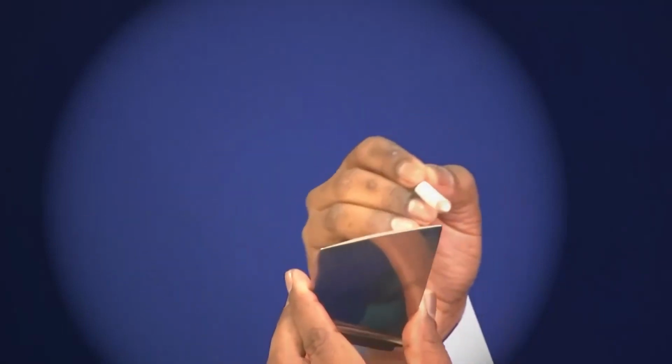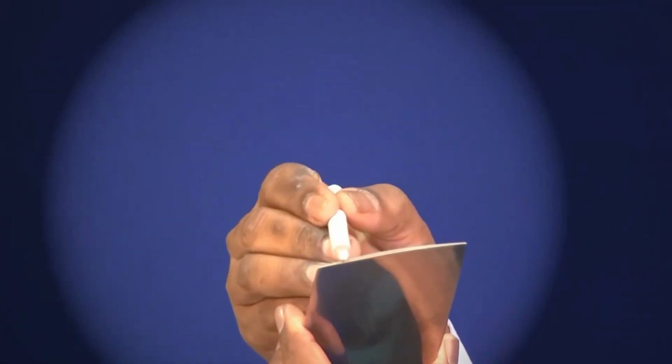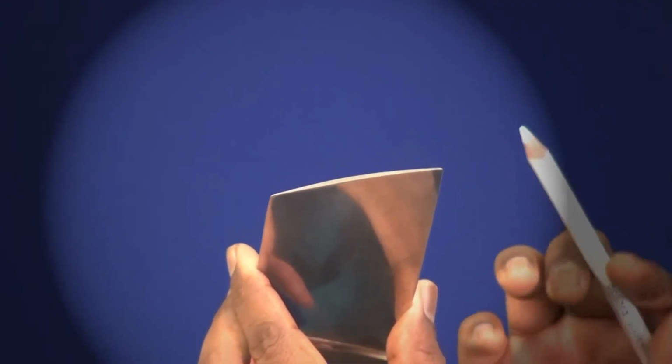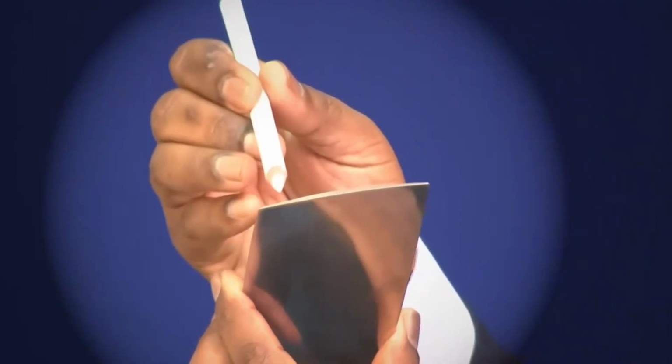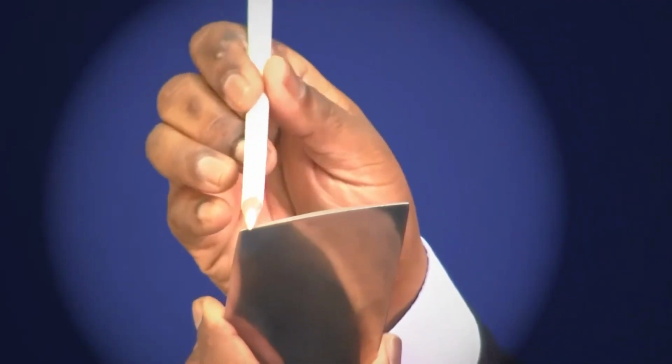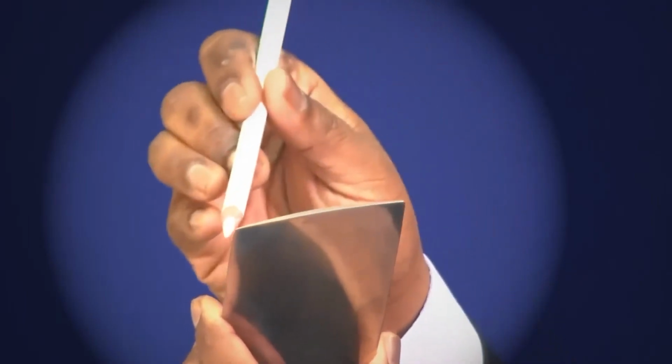This blade has a different kind of pressure surface and suction surface. It is a transonic blade for an LP compressor or LP fan, it has less thickness, and it has a double circular arc.